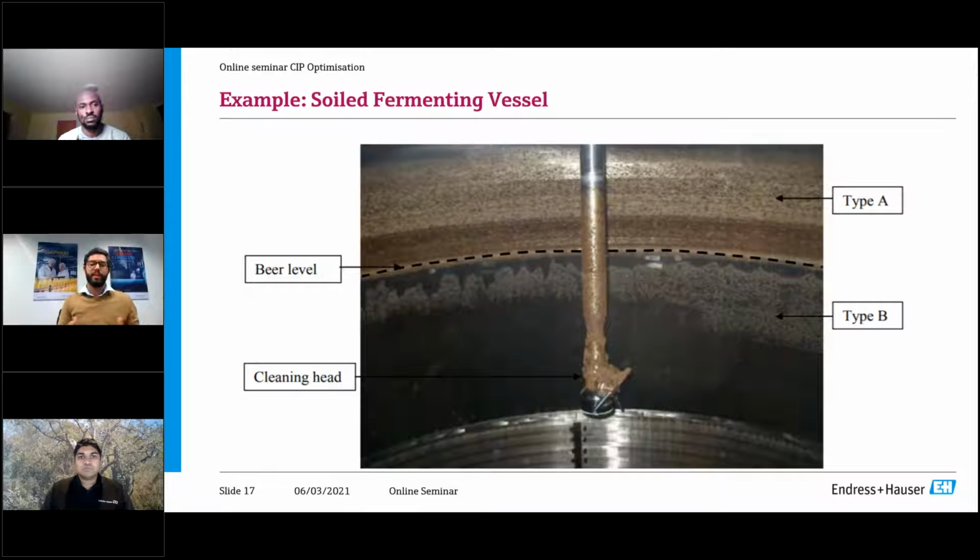Well, in the food and beverage industry, as in any other type of industry, we can have different types of soiling, and each type of soiling has a very specific challenge. And what we do know is the soiling condition is time dependent, and it's also process dependent. So if the soiling is exposed to high temperature, it will get into a condition that will be harder to clean. Still, the majority of customers still use a time constant approach for the cleaning.